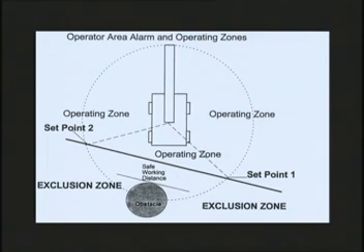By setting the left and right points, each one 10 feet away from the wall of the building, an invisible wall is created that passes through both of these points and is located 10 feet off the wall of the building. Then, when operating the crane, an alarm will sound any time the boom tip is moved nearer to the building wall than 10 feet, or past the invisible wall. This happens regardless of which functions are causing the boom tip to move closer to the wall. Detailed information on setup is contained in the operator's manual.